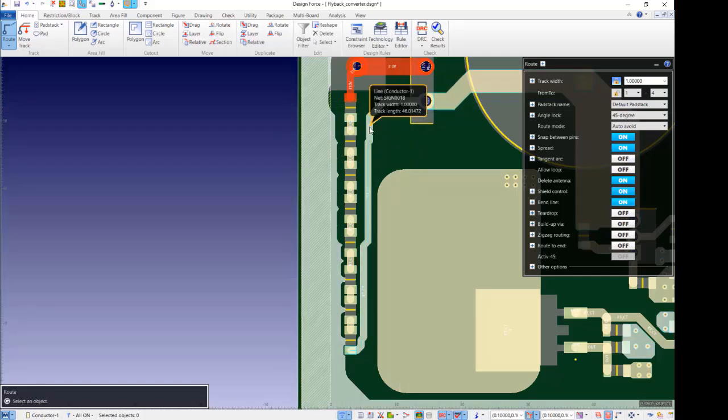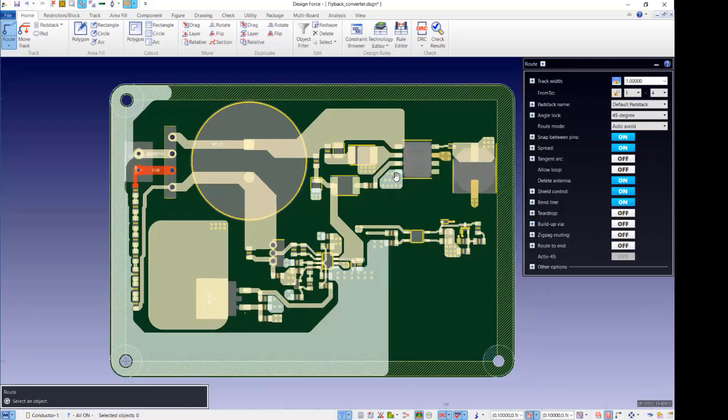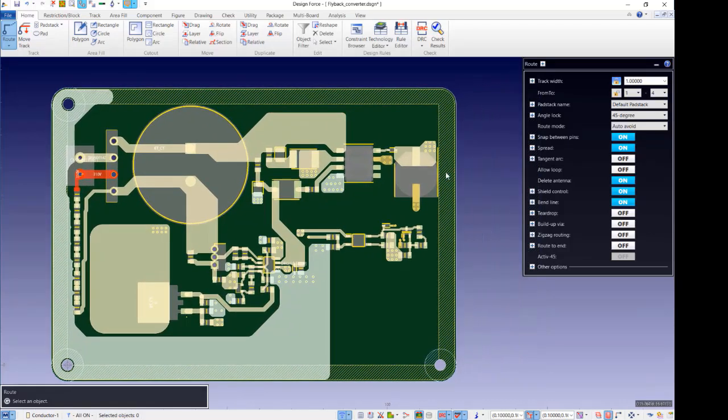the different steps, and obviously this gap and this gap will be the same, okay, because this potential and this potential is the same. So that's how you can see that the voltage difference has actually now controlled the space in here. The other thing we did at the schematic side was that we put in all of the nets in my primary section over here into a clearance class called primary, and all the nets on this side in a clearance class called secondary.